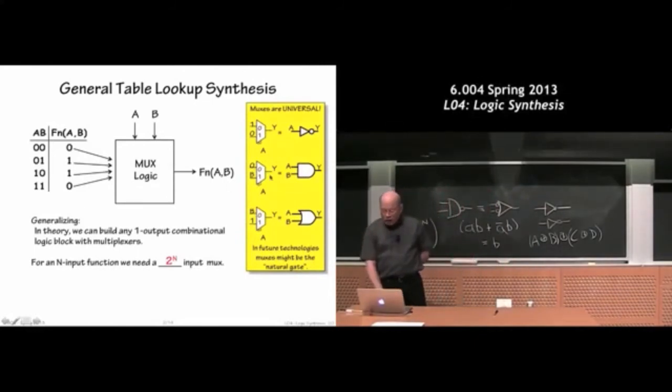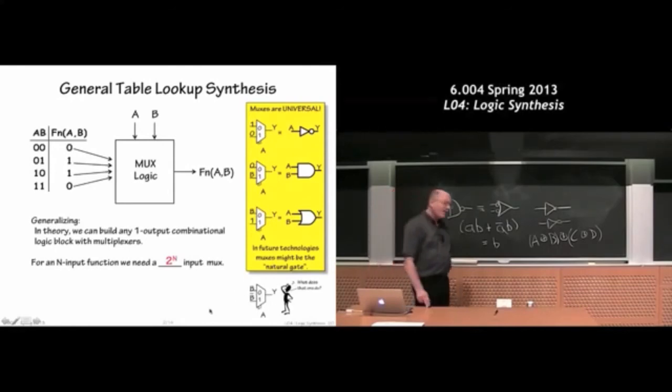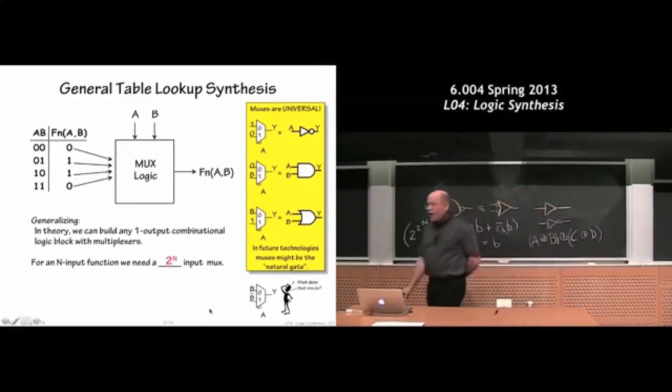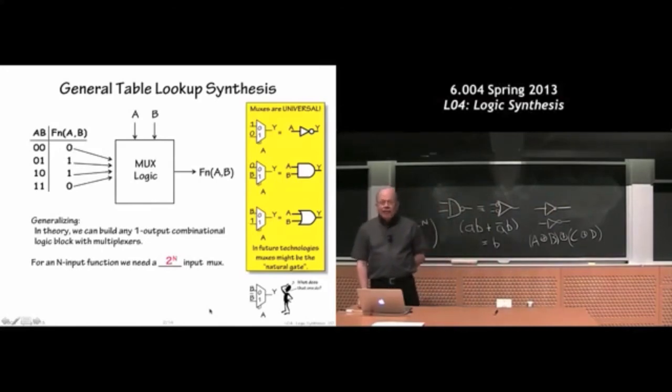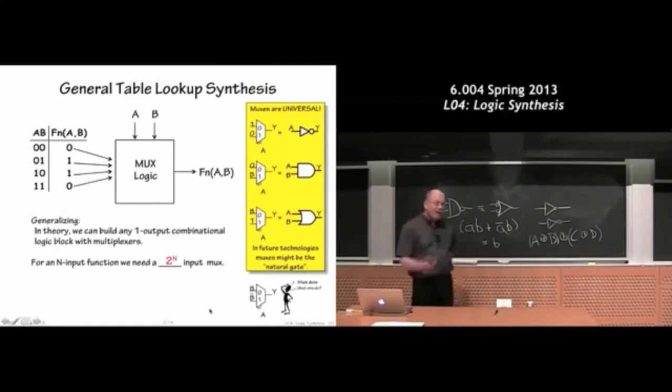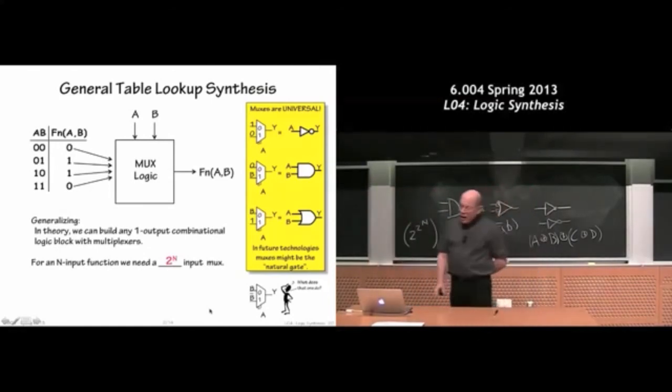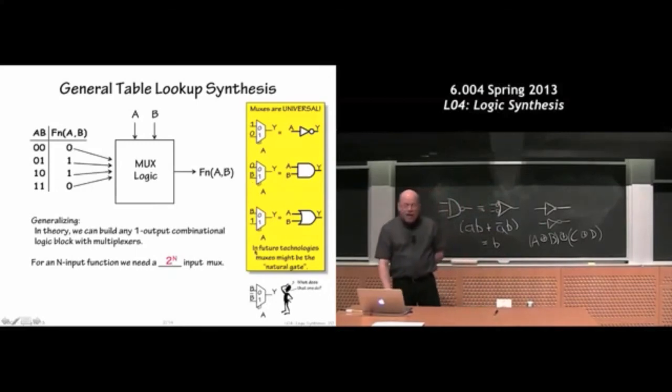On the other hand, here's an example of why muxes are universal. Think about this logic gate, which normally takes about 10 FETs to implement, but which we implement quite compactly here in this mux. Things like carbon nanotubes, which everybody's sort of hot on these days as a possible way of building very neat, almost molecular scale logic, I think they naturally implement a multiplexer as the thing that they do quite well. So.